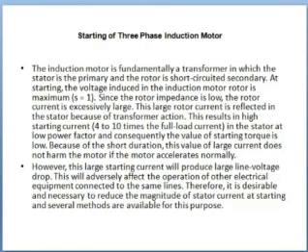But for a DC motor or induction motor, it takes time to generate back EMF because the back EMF depends on the speed of the motor. That's why it takes some time to reach steady state speed, and to generate the back EMF it takes much time, and during that time the starting current of the motor is dangerously high. That's why we have to use a starter, so that we can minimize the starting current.